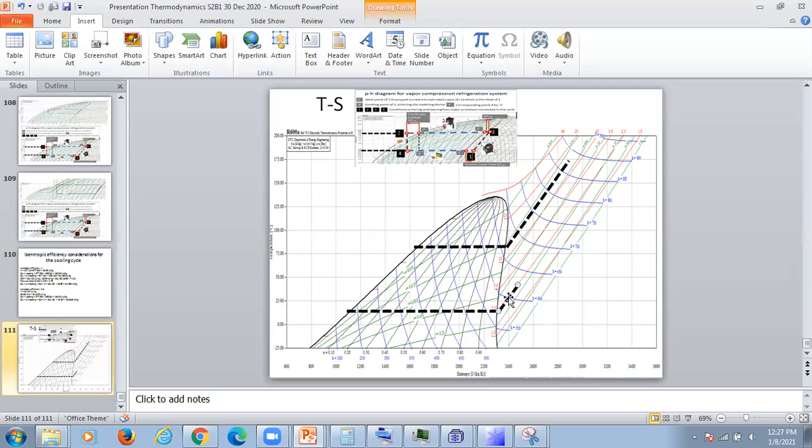So after that, the compression starts isentropic. It comes here. So this point will not go till then. It drops like here. Okay. So here, some cooling, temperature dropping, entropy dropping, constant pressure line remain. Okay, something like this maybe.